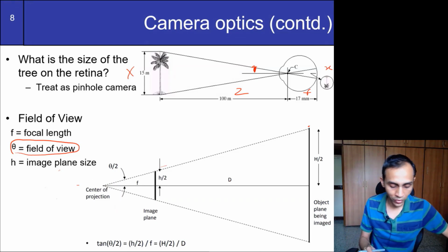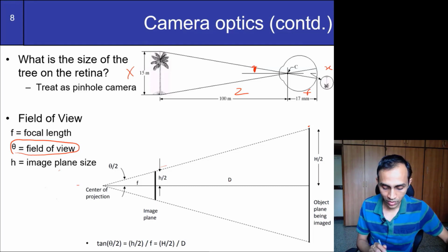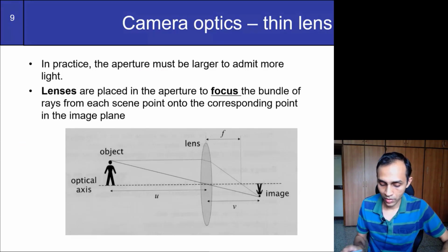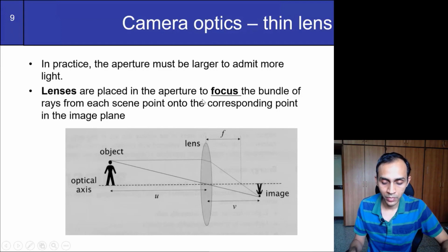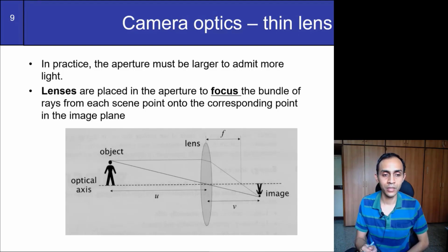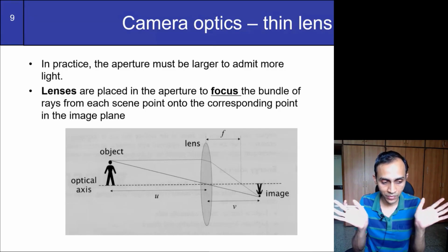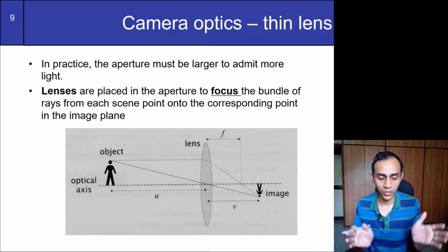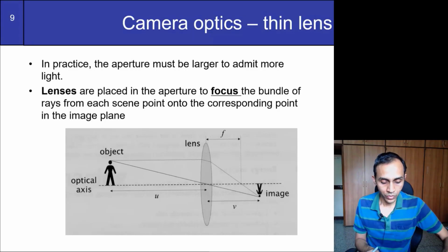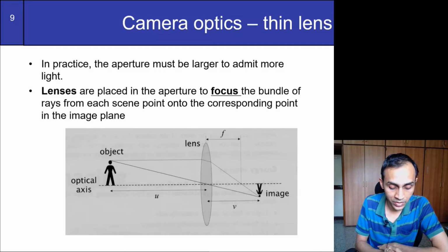So those are related to camera specs. Just for your practical information, if you're going to purchase a camera, these are important specs that you should think about depending on your requirement. If you are going to use a camera for an image processing or computer vision application, for example, when we had to use a camera for our classroom, we had to go for a wide angle camera. If you want to capture the entire classroom scene in just one camera, then we have to go for a wide angle camera which has probably a 180-degree field of view, or as large as possible, 120-degree field of view. So those specs are needed to be aware of, depending on the application and your requirement.